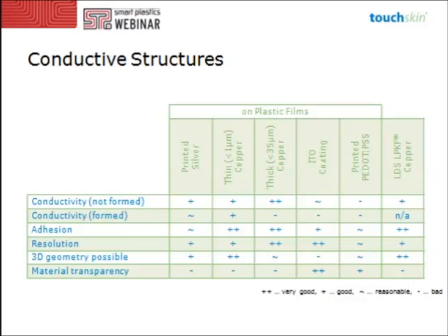This is a disadvantage, but it has a rather good conductivity and it is perfectly transparent. All the other candidates from the material standpoint, like silver and copper, are not transparent. PEDOT:PSS is a polymer which is transparent. It has a somewhat bluish color, but it is transparent. But all the other parameters are not so good for PEDOT:PSS, so it is not so much used finally.